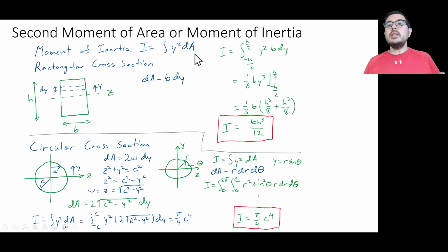If the density is constant across these cross sections, which it often is when they're solid and made of one material, then we can say, if I know what the density is, I can incorporate a mass in there, and I can calculate what the inertia will be. And so they end up being the same just by a scaling factor.